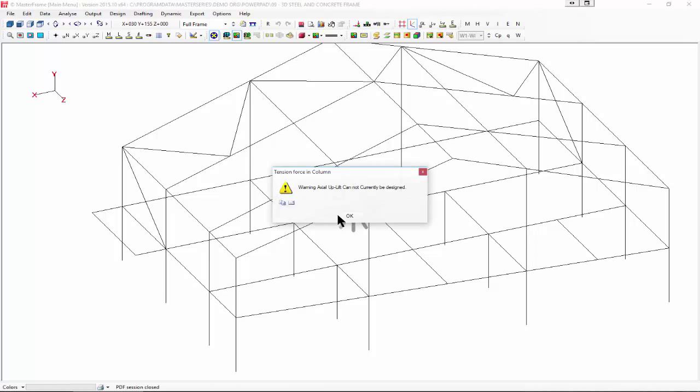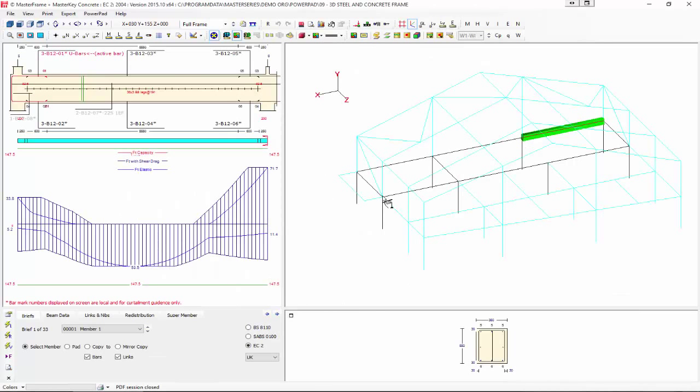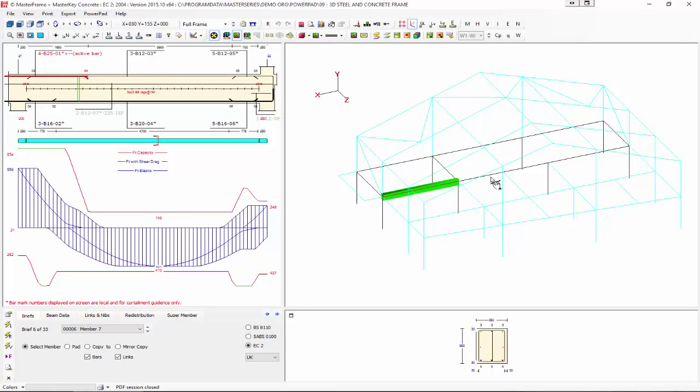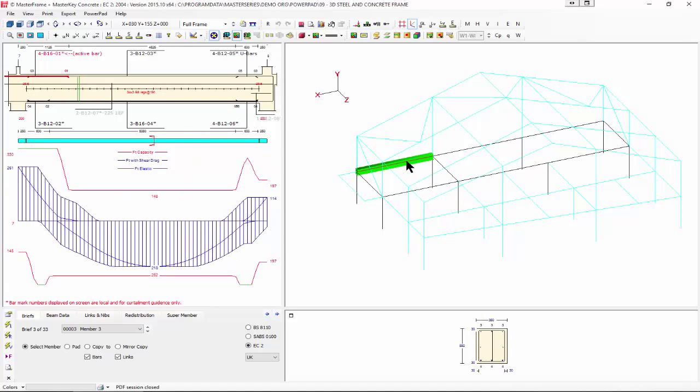And it's now running through. And I can look at these members here and design those for the reinforcement. Obviously, it's not necessarily the best example, but we are getting our lovely reinforcement here, 416s down to 312s, well, maybe go up to 412s at the mid-spans for our continuity links and reinforcement. But we do only have 3 links, so possibly, yeah, it was right.